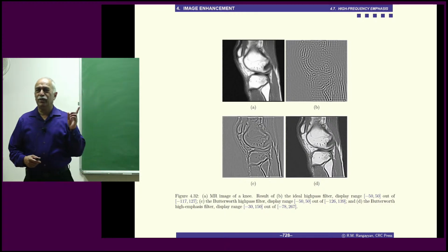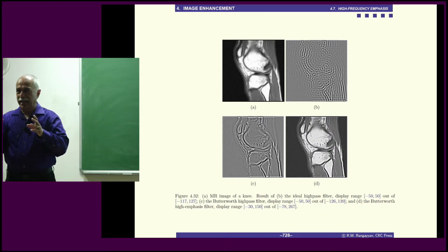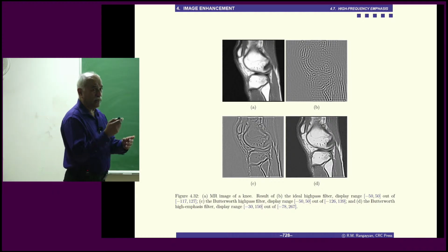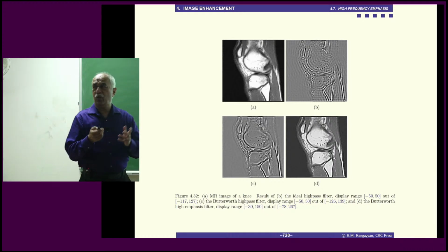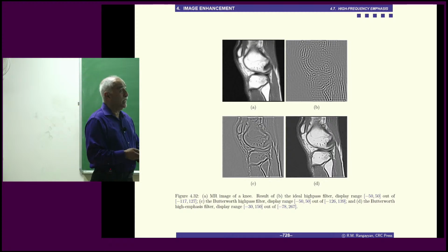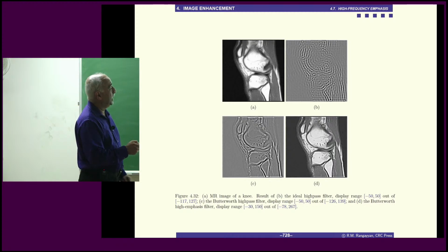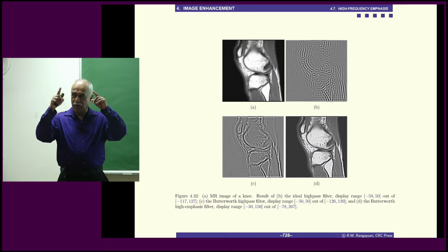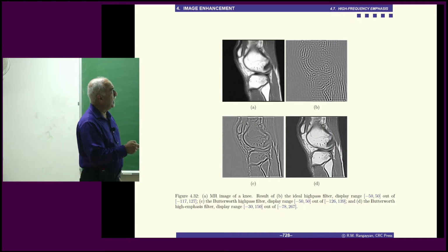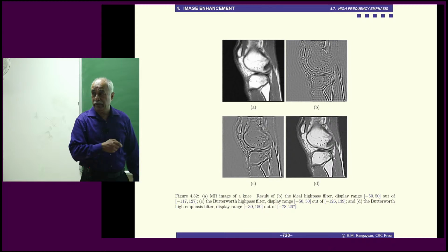In some of my other images, I had to do zero padding because of the size of the image being some odd shape or some different numbers other than a square. So to compute the DFT through FFT, I had padded zeros, and the borders also gave some ringing artifacts. In this case, the ringing artifacts are clearly related to these edges that are present in the image.